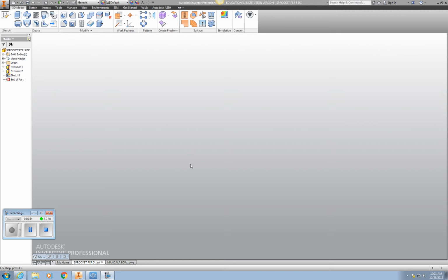Now, as we look at it carefully, this particular drawing has a lot of circles, a lot of diameters, and we're also going to be using several new commands. One of those is called circular, which in AutoCAD terms is called a polar array, which will allow us to draw any geometric shape around a center axis. So to begin the drawing, we're going to look at the front view, and we see in the middle a 32 diameter circle, and the next larger circle is a 63 diameter.